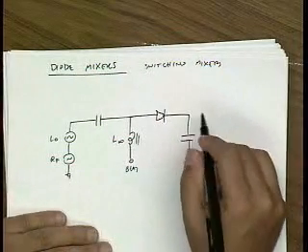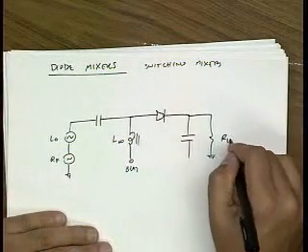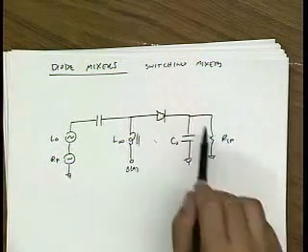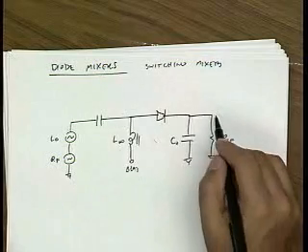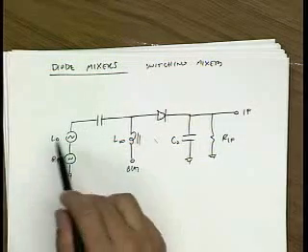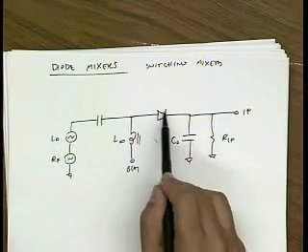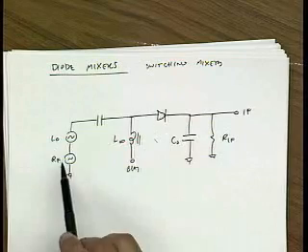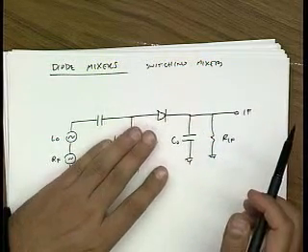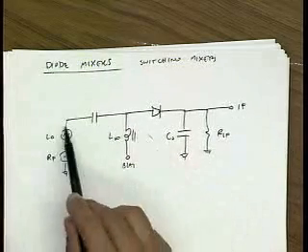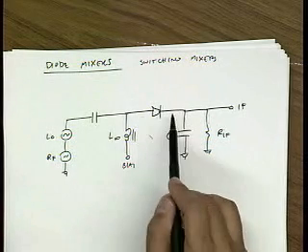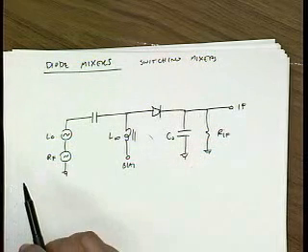And I bias up my diode so it's turned on and conducting some current. And the assumption here is that the LO signal is quite large, and so it can basically turn this diode on and off. So the equivalent circuit seen from the LO port doesn't see this signal here because this is the large LO choke, and so it just sees a diode. And if the LO swing is sufficiently large, it just turns this diode on and off. It looks like a rectifier, right?